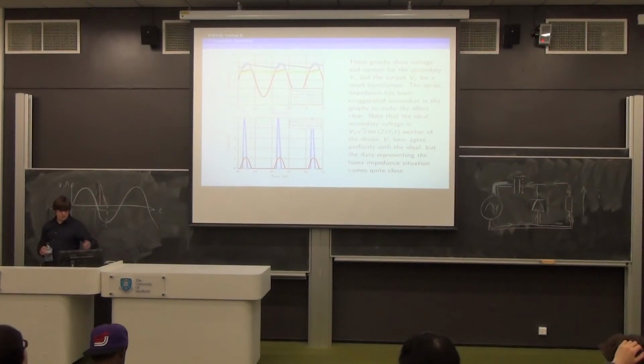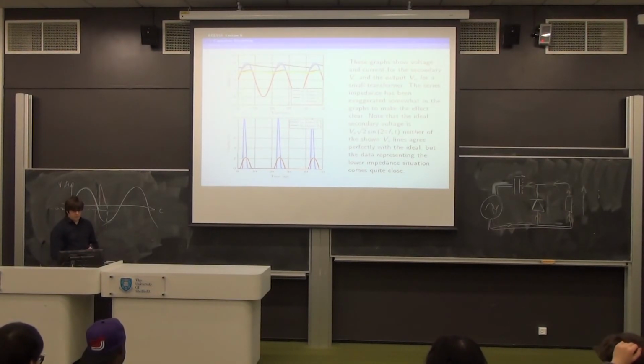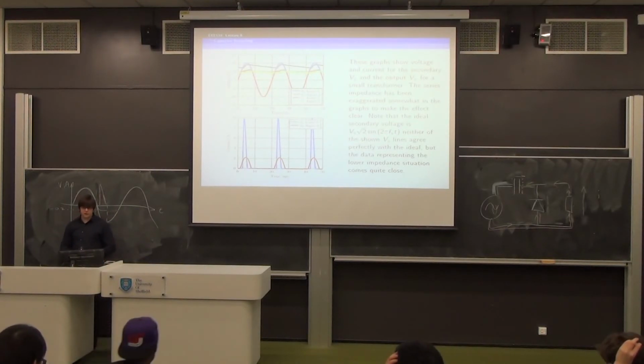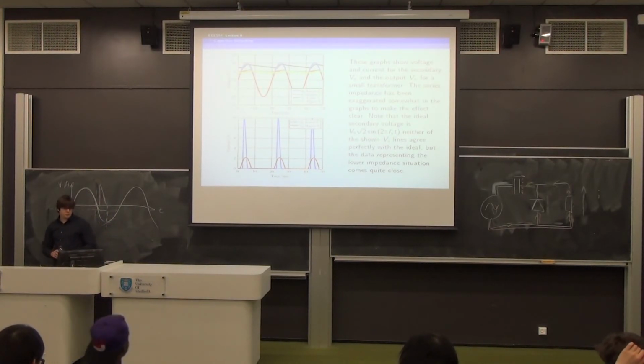the half wave rectifier, where it's once only per input cycle. We can see it's charged up between 2 and 6 milliseconds, and then again between 22 and 26 or thereabouts. So that's once per input cycle. That's really, mathematically speaking, the only difference. Electrically they work broadly the same, except one is an extension of the other.